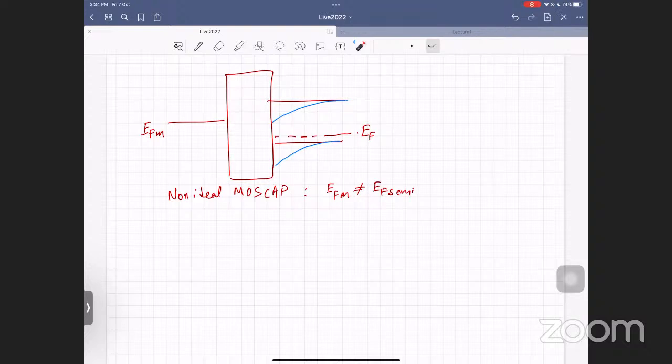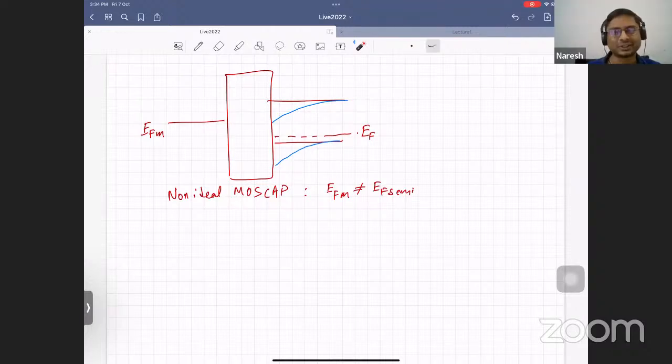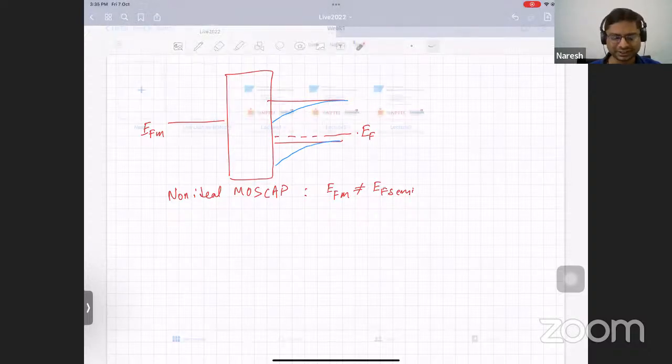If the MOSFET technology mentioned is 180 nanometers, will the channel length be 180 nanometers? Well, I think I talked about it maybe in week 8 or week 10, when we talked about scaling. In the olden days, before 2000, it was true. When you said 180 nanometer technology, the channel length was more or less 180 nanometers. But starting about 2005 or so, or even slightly earlier, the channel lengths were not able to keep up with the technology names. I talked about the scaling part in detail in week 10, I believe.